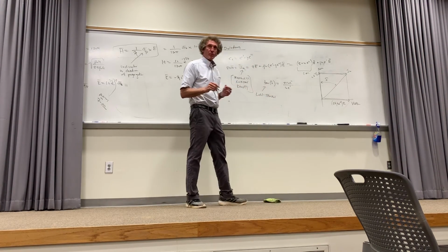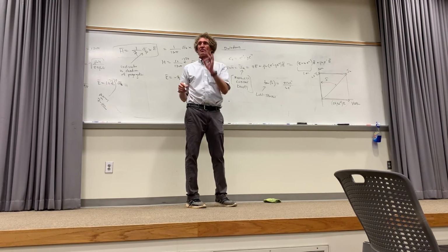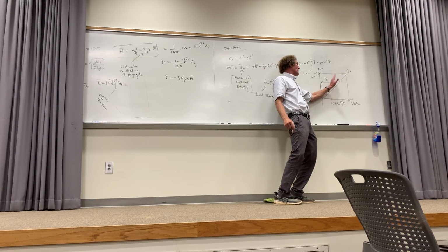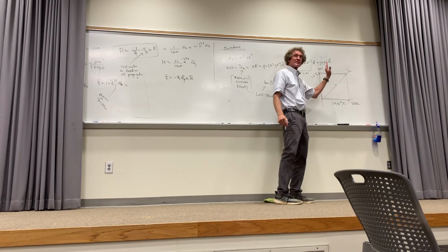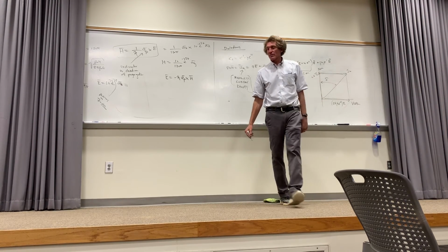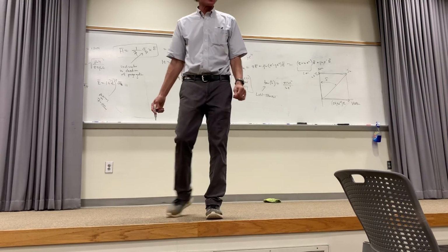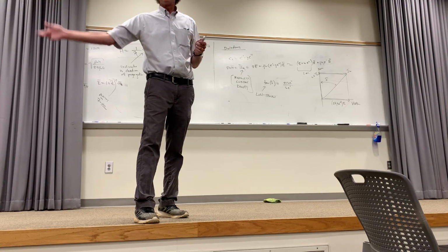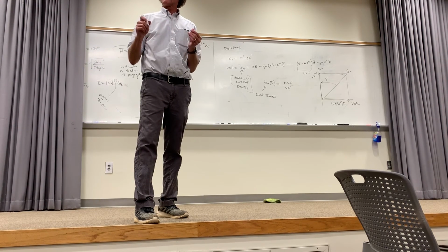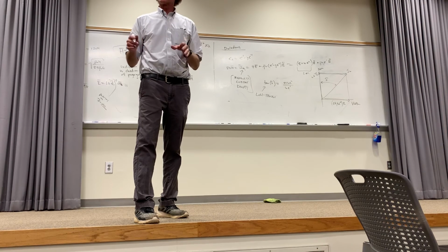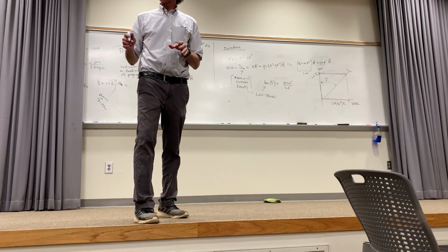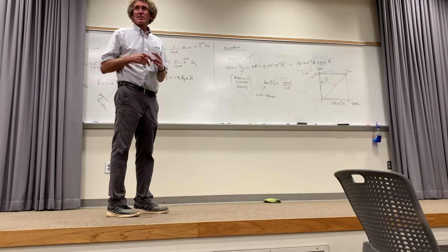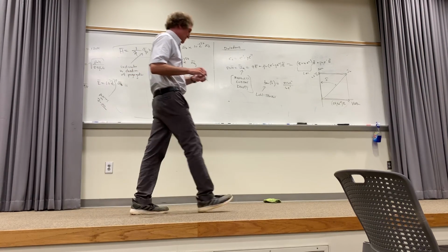Now here's why this is important. We'd like a loss tangent of 0. We would like no loss at all if we have a dielectric and we want it to behave as a dielectric. What we'd like is that angle to be 0, but it's not. So the loss tangent itself is an indication of how good of a dielectric it is. When you get loss tangents down there at, and it's a function of frequency, 0.0005, like 5 times 10 to the minus fourth, that's good material. That's low loss at that frequency. You get materials with a loss tangent like 0.1, 0.2, you've got a problem. You're losing a lot of power. You're losing a lot of signal. Just remember that as a gauge.